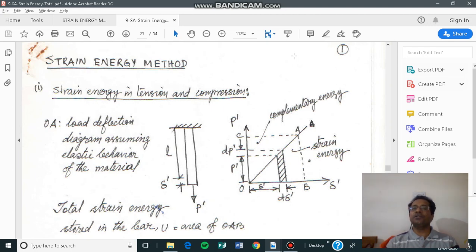That means here the relation between the external load and the internal forces, and you are using the concept of energy to get the slopes and deflection. In this concept of energy, there are multiple methods. The first method you will learn is the strain energy method. To use the strain energy method, let us have some brief idea: how can you compute the strain energy for the different internal forces and the deformations?